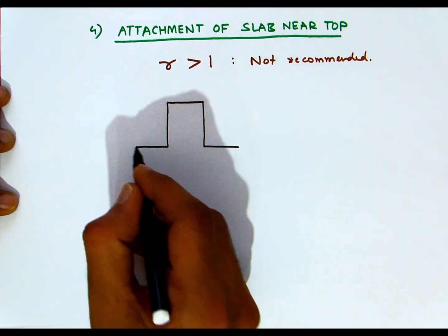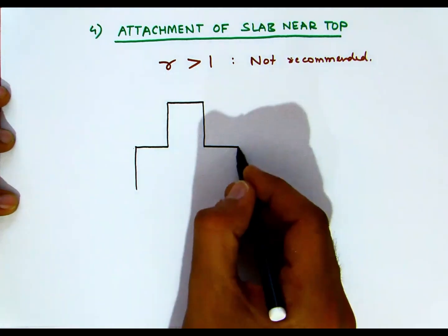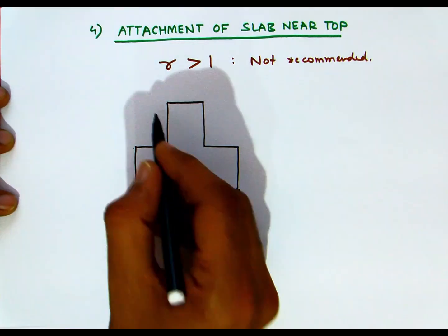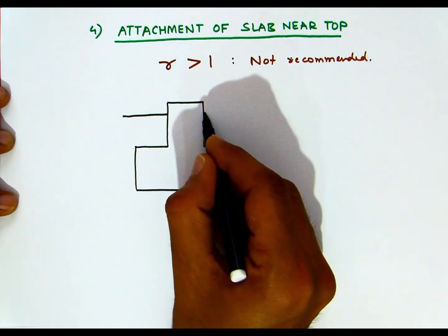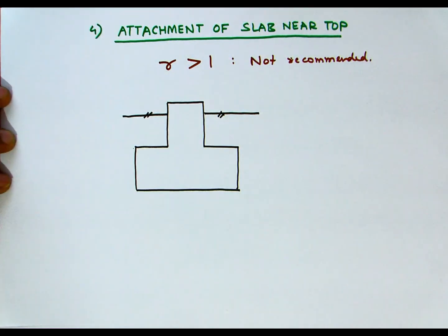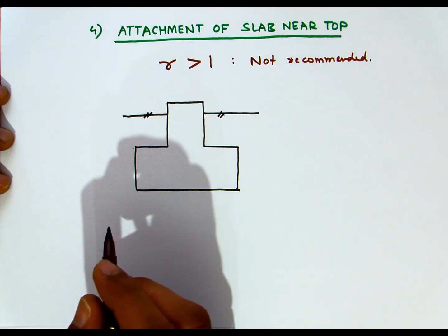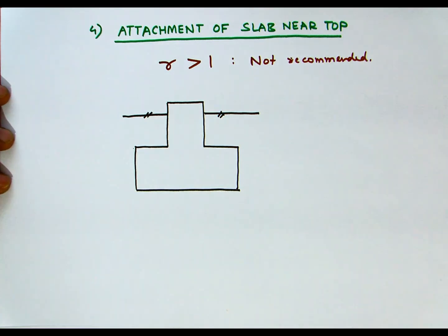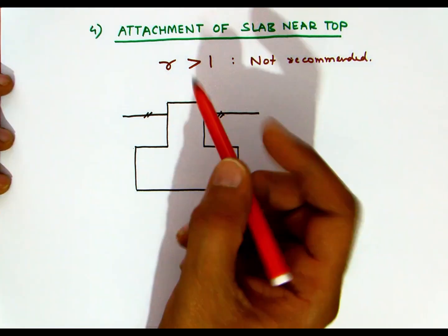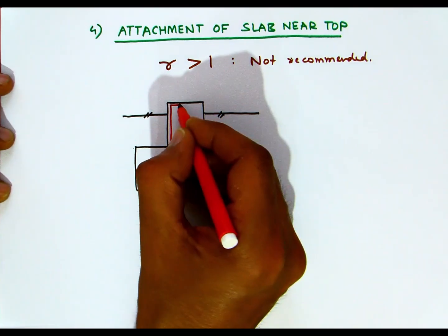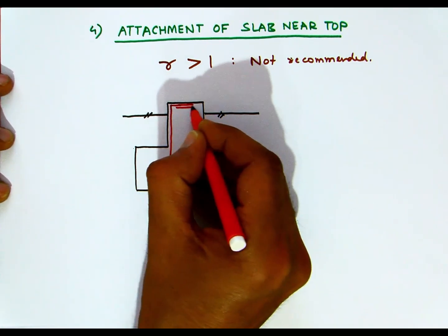As compared to the previous two measures, that is soil stabilization and increase in the area of the base of the foundation, this measure does not require excavation to the full depth of the foundation. It only requires excavation near the top pedestal, and as such it poses less danger to disturbing the alignment of the foundation system. So here we are showing the foundation block and the pedestal.